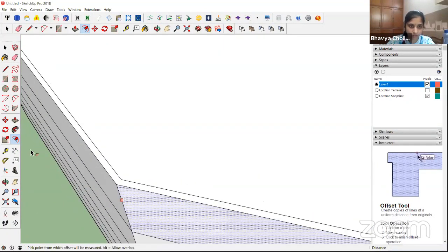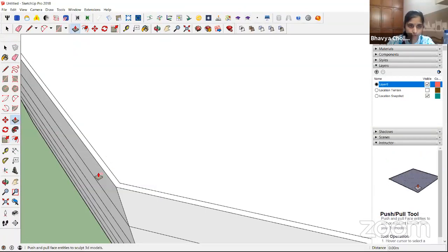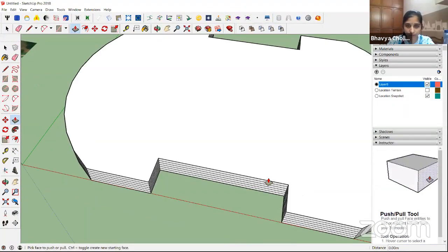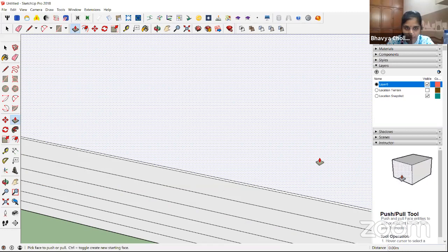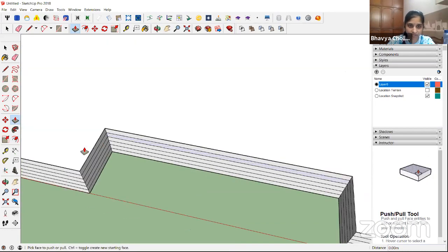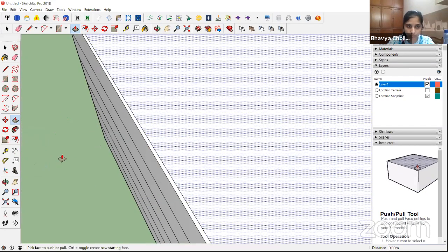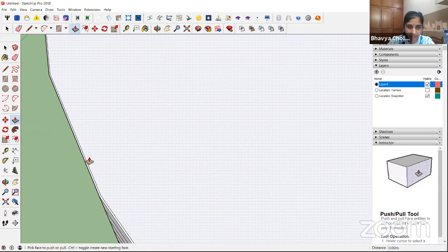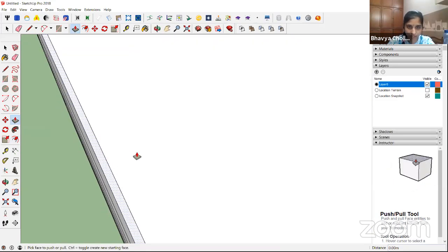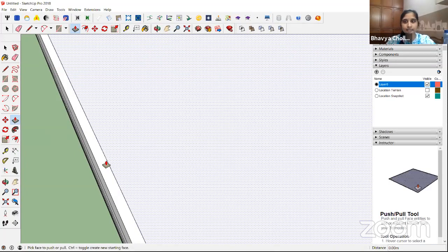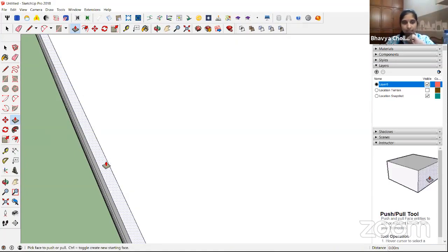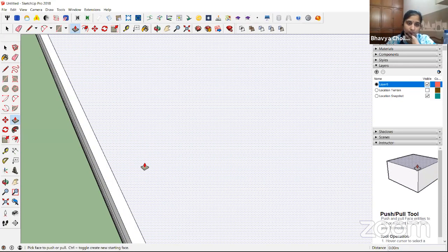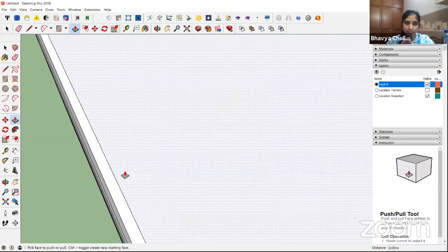Okay. Now I'll use the push pull option. Now let me see whether I've got the complete railing or not. You can see it is everywhere, right? Because I've considered it at the start. Now I'm using a push pull option. Zoom in, guys, and you can see there's a dotted line here. Now you want to increase the railing to some extent. For that purpose, you have to see which part is getting selected. I'm just moving my mouse onto the screen, guys.